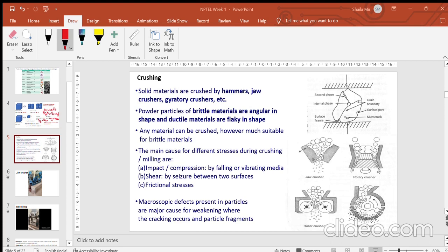Now, first talking about ball milling, this is something that is largely done for manufacturing in powder metallurgy. Ball milling has certain parameters that need to be understood. For example, for a ball mill, you need to know the ratio of your balls to the feed material. For example, you are crushing a certain material A of 10 grams. Now, how many balls you need to put against this 10 grams needs to be identified, because you cannot load the ball mill to its 100% capacity.